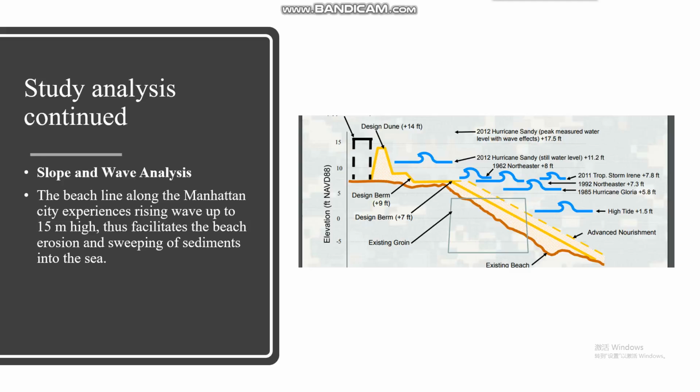So what we can see is that in 2012 Hurricane Sandy made the water level hit the peak of 17.5 feet. So the design I chose is to use the sand wall or the rock wall to be 14 feet high.